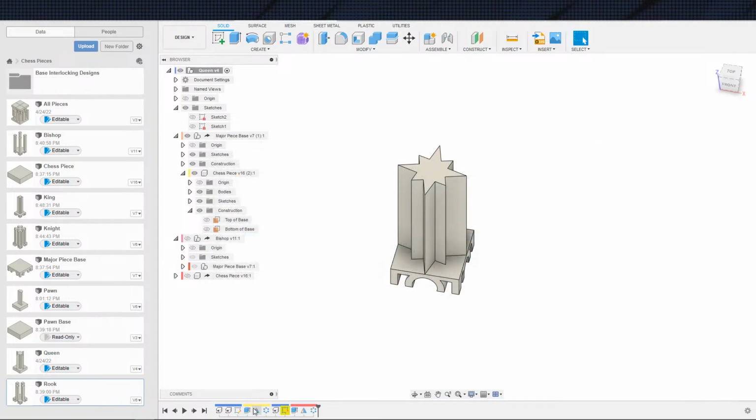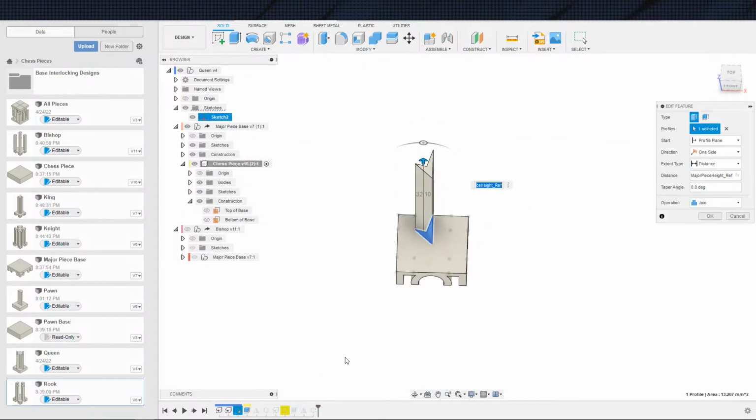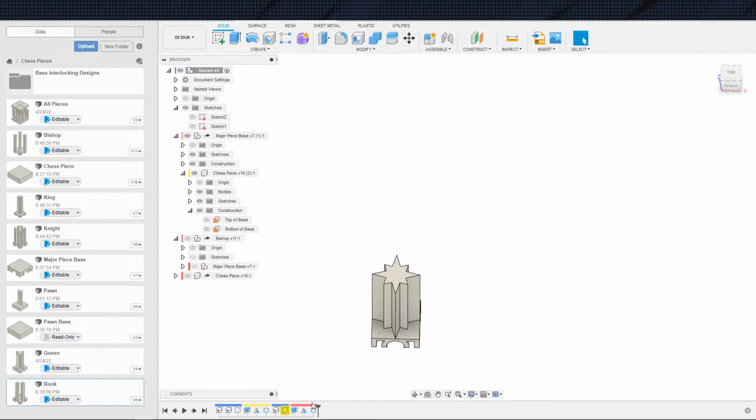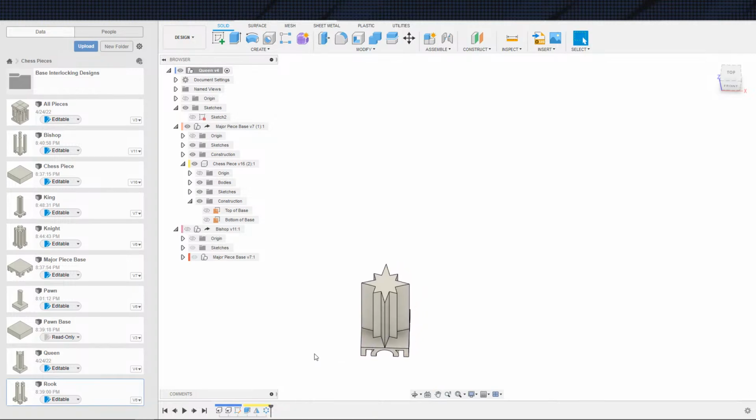Oh. Huh. Oh, I don't know. I'm guessing what's going on here is that, obviously, it was only the sketch that was screwed up. Because only the sketch was screwed up, the extrusion was still going off of the old number, but from the base it was 6 millimeters shorter. So that would explain why those two pieces did not overlap. There we go. That explains that one. So we go ahead and save this one.